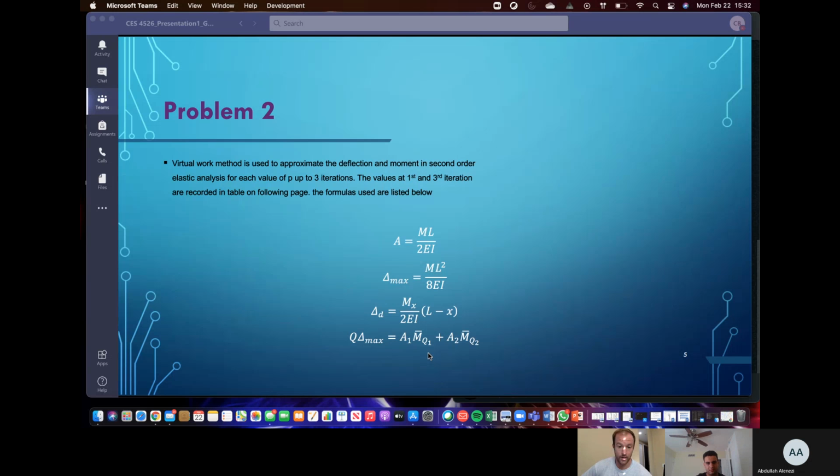It's divided into 4 areas, but it's a mirror image over the center point. So really, we only have to do calculations for 2 areas. Now, these areas are both going to be trapezoids, since we already have that moment right off the bat on each end. So we calculate the area and the centroid, just using the proper formulas for a trapezoid.